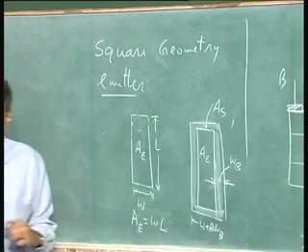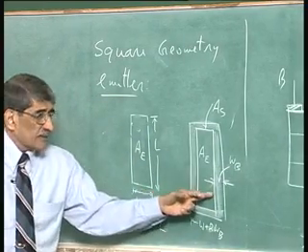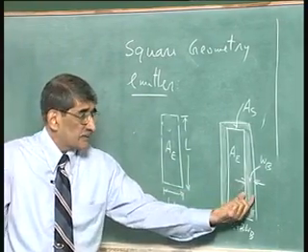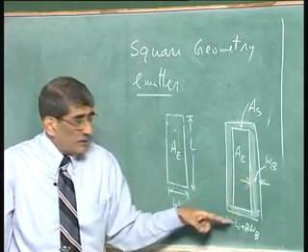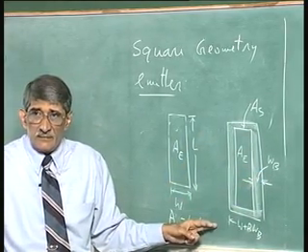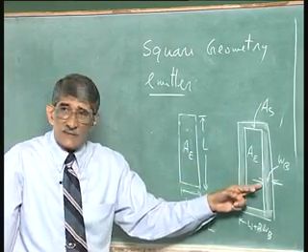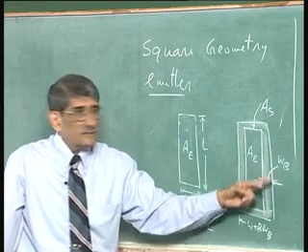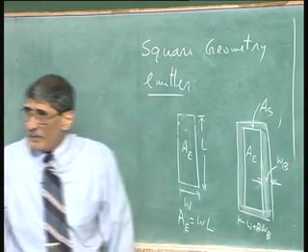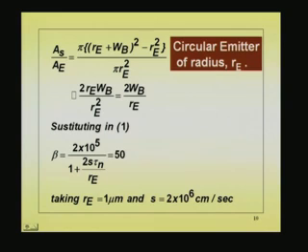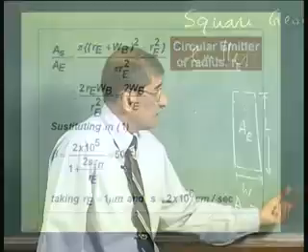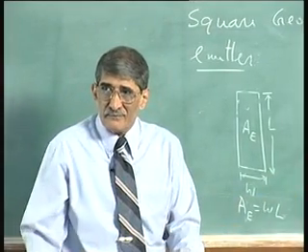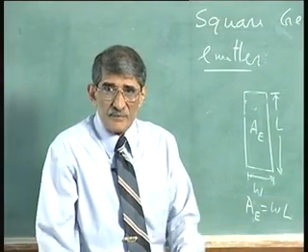So the key thing to note is that you find out the recombination current here by finding out the width which is equal to base width and see what the area is, and the carrier concentration is NP0 here, 0 at the other edge corresponding to that. So, this is just as an example. If you have to calculate the beta of the transistor or a square geometry device, all that you have to do is find out that periphery area of width equal to WB.